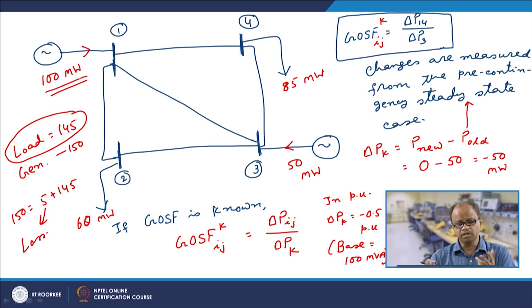So in that case, if we have to prevent the complete shutdown of the system, we have to essentially resort to load shedding, which we do not want to do. Obviously, resorting to load shedding should be our least priority. So whenever we say that some generator is out, we must also say that there is some mechanism to compensate for this loss of generation.